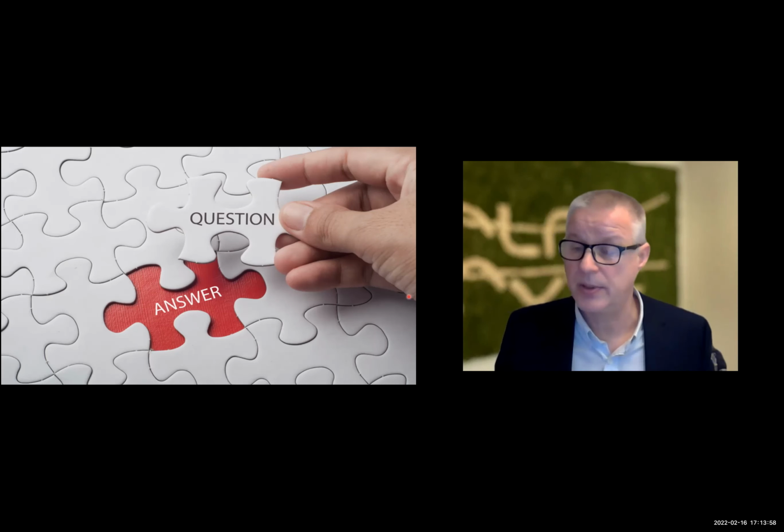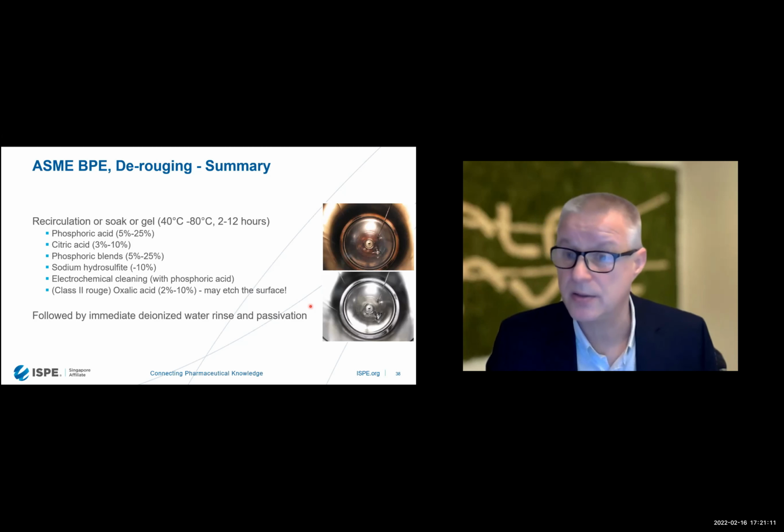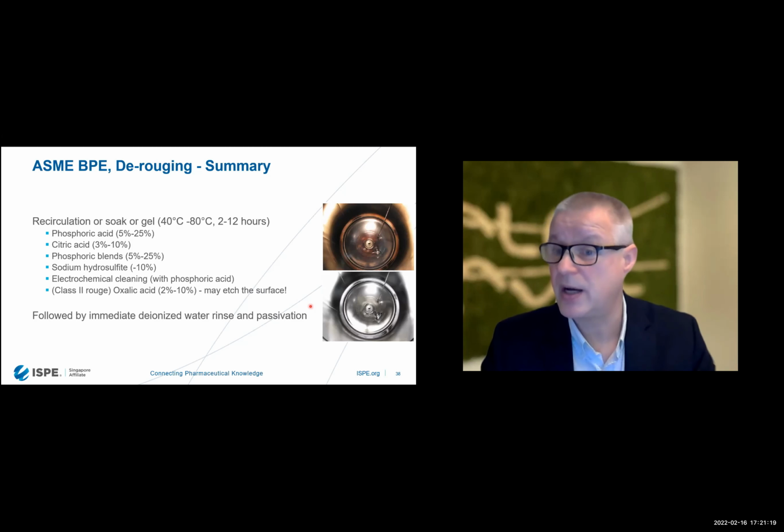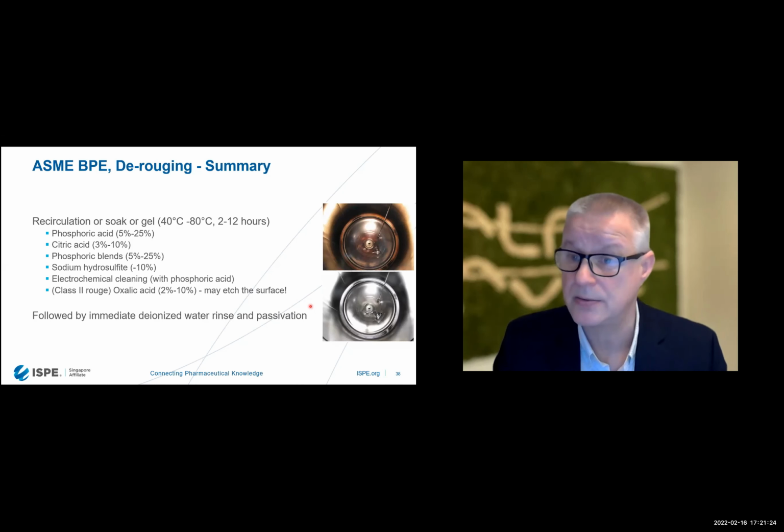And because you replace this filter every time, you also see if you have rouge particles in it. So I would say the best way of measuring is actually to check the filter every time you replace it, and it's the cheapest way. You still need to have the filter anyhow, and then you have a very high frequency of inspection. So that's probably my recommendation.